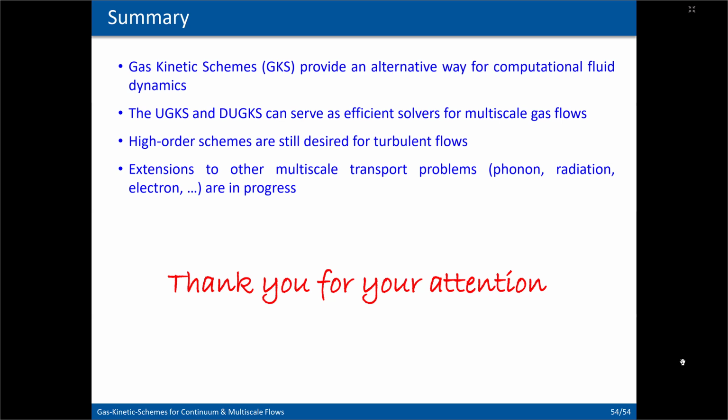Actually, perhaps this is a common problem for discrete velocity methods. For flows with a large Knudsen number, we must use discrete velocities covering a wide range, particularly for high Mach numbers. And for highly rarefied gas flow, we also need a large discrete velocity range. So the computation cost can be reduced by optimizing the discretization of the velocity space. Perhaps a self-adaptive particle velocity can be adopted. Yeah. Okay.